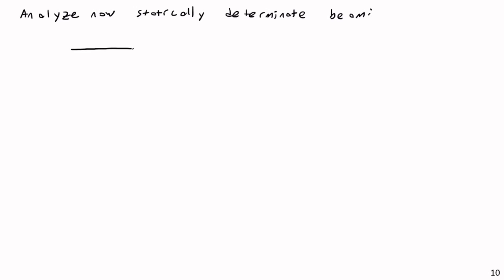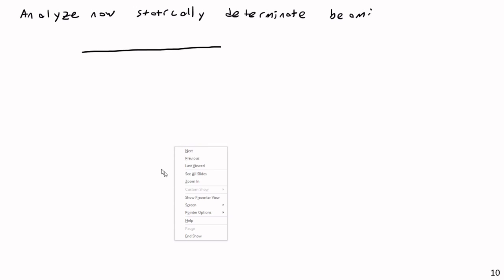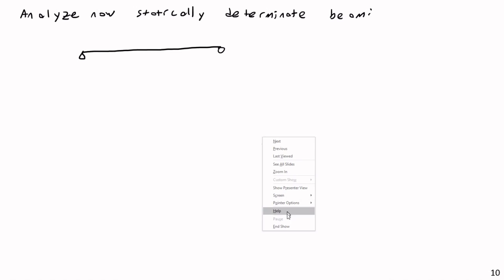I could draw this as a fixed beam, but actually I can just go ahead and draw this as a simply supported beam. So this is effectively a simply supported beam now, with the following loads on it. Let's trust but verify and see if we can actually confirm which direction AY and BY will be in, because we are putting the redundant reactions back on, AY and BY.